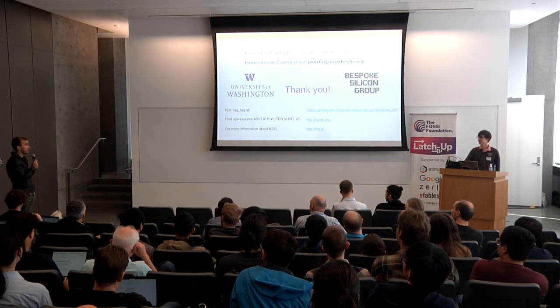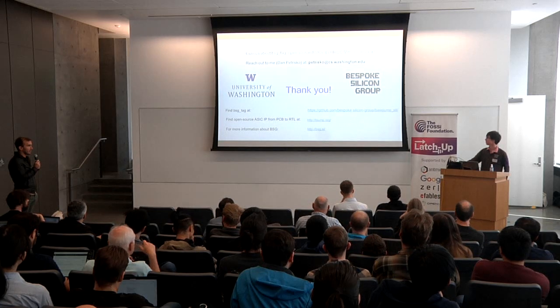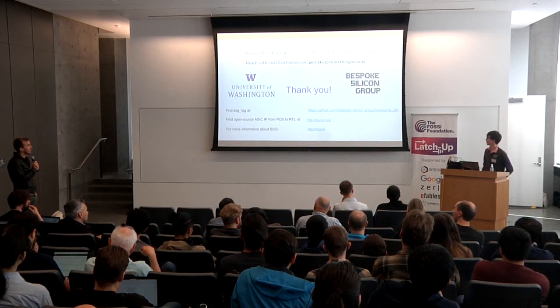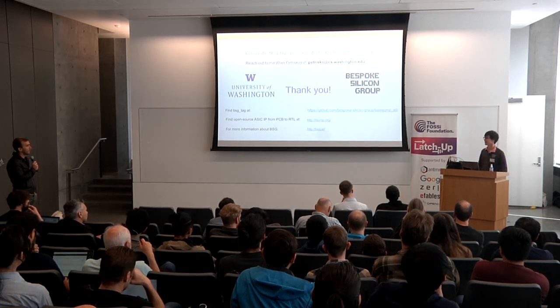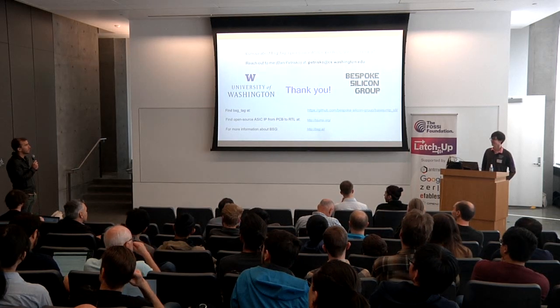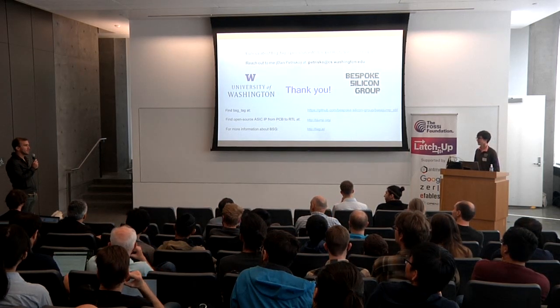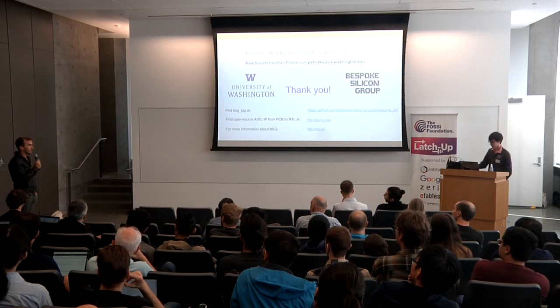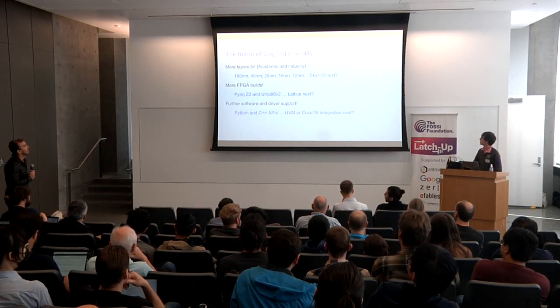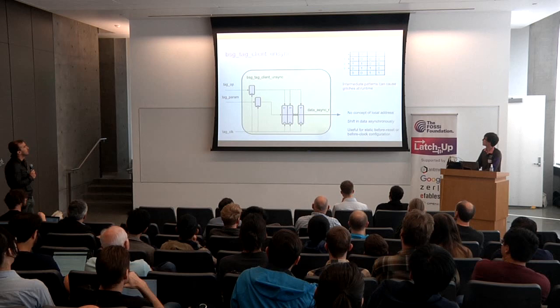And you guys put this in all of your silicon now, right? Oh yeah, many times. We just brought up a chip with it actually a month ago. Cool. And how do you deal with the source synchronous thing? I always cheat and just shift the data on the negative edge and sample on the positive edge or whatever. Yeah, that's effectively how it works.